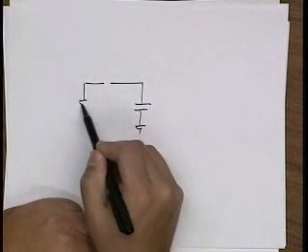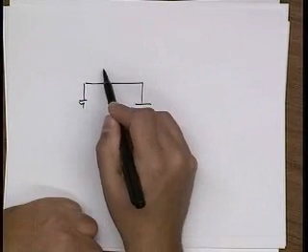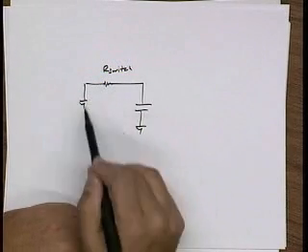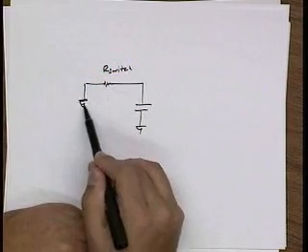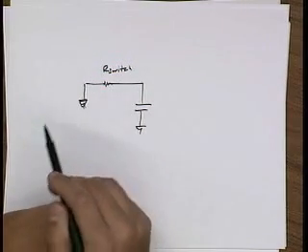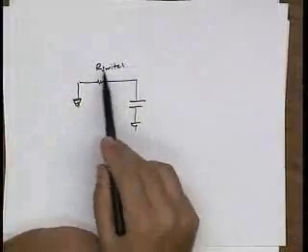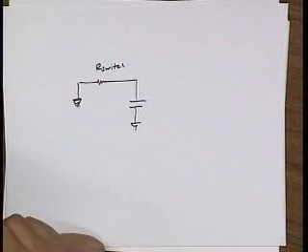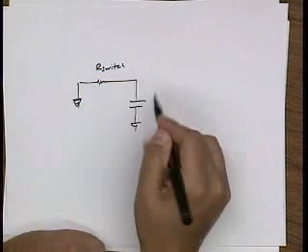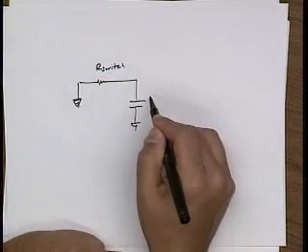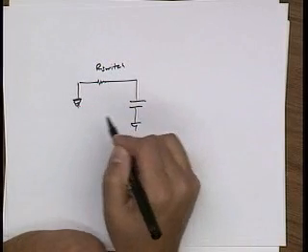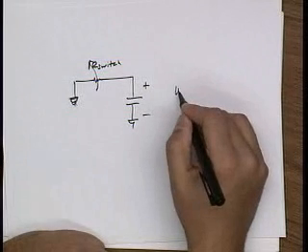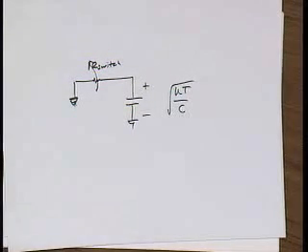So what I'm doing is, this is the R switch, right? And so I'm shorting my device with this R switch. Now you had a good guess. You said it's going to be 4 KT R switch, but that's the spot frequency, right? At the end of the day, when I'm done, there's just going to be a voltage across here, right? Because then I open the switch. And so when I open the switch, the noise that stays here is going to have variance KT over C, right?